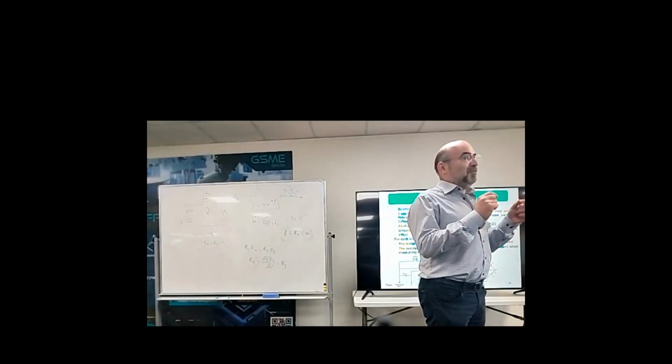Do you remember what is needed for a Wheatstone bridge to be balanced? Basically, if you look at this as a voltage divider, whatever it divides, the voltage at C equals the voltage at D, then you measure zero. It's very useful, particularly in old measurement tools and any measurement tool, because measuring zero can be very precise. If you want to measure any number, it depends on the scale. But when it comes to exact zero, if you have a sensitive voltmeter, you know when it's zero, so you cannot have any error detecting this.